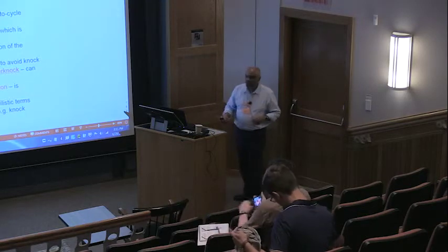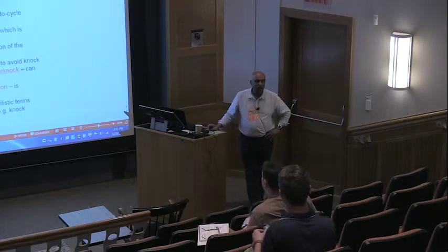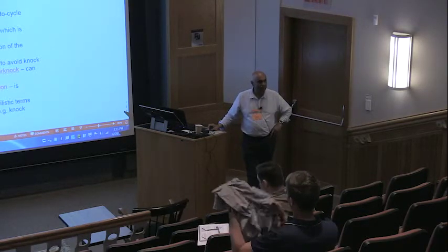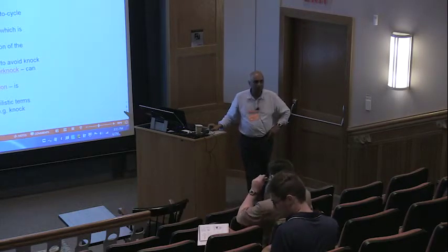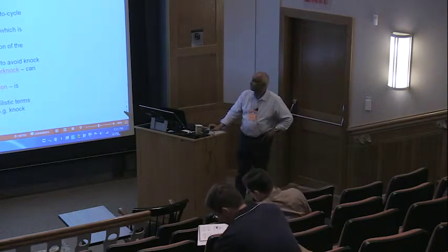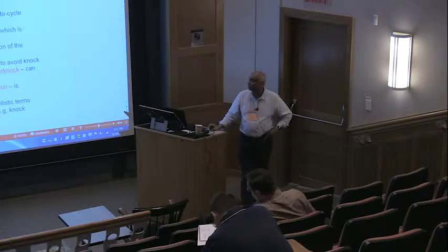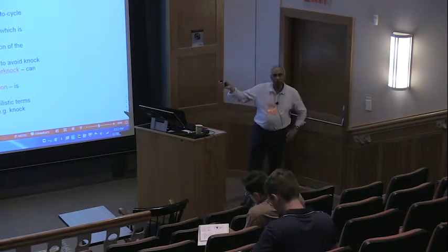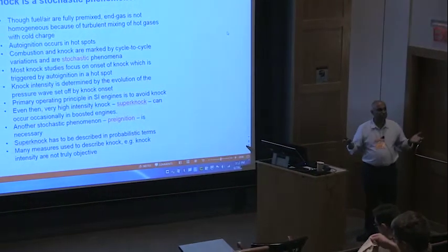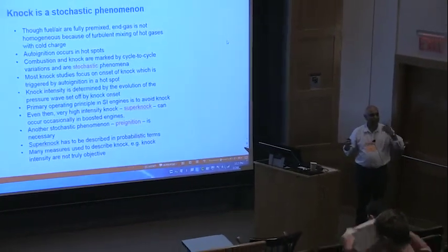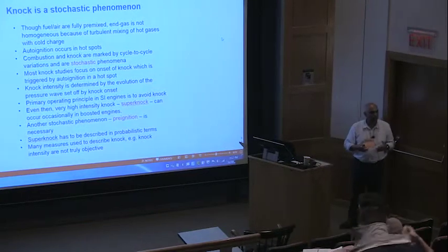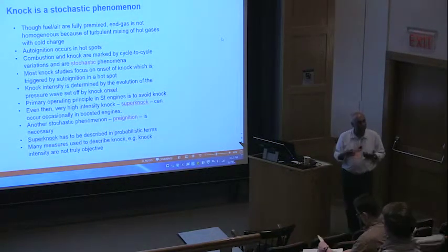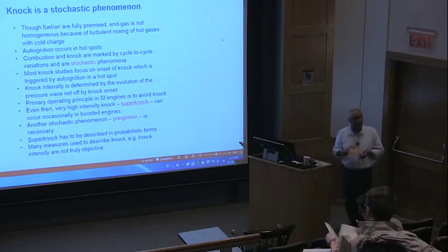First thing you have to remember is knock, like any other engine operating parameter, is a very stochastic phenomenon. For example, in all the things that I said before, we were just assuming the fuel and air is pre-mixed and auto ignition occurs and everything happens at once. But that is not the case.